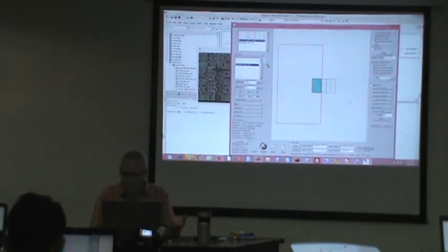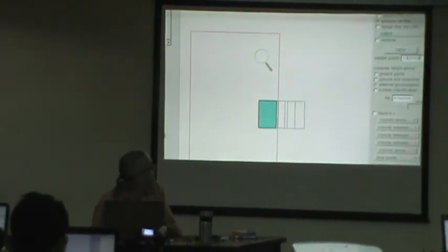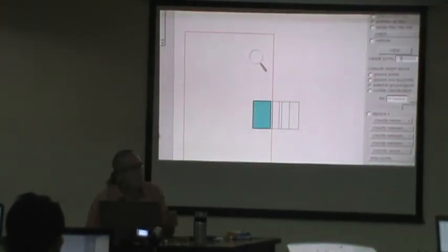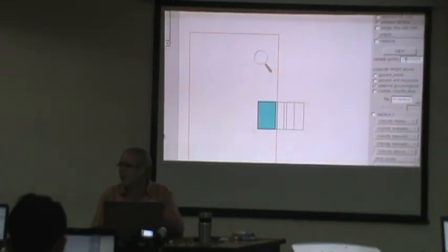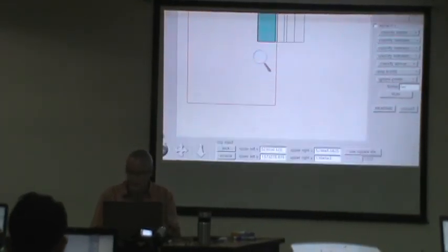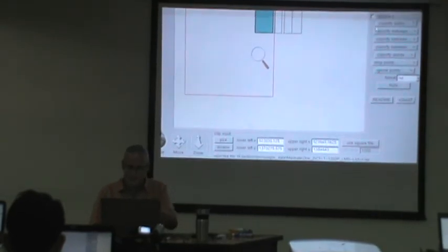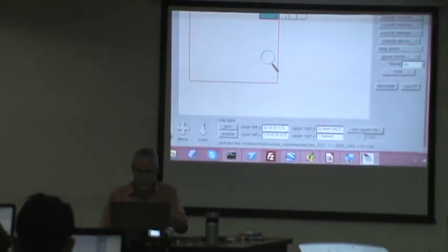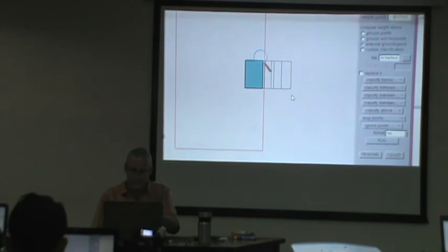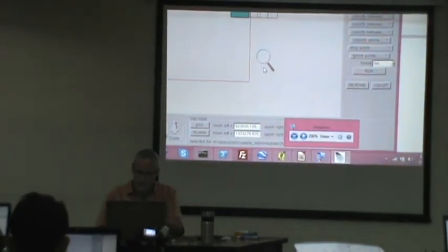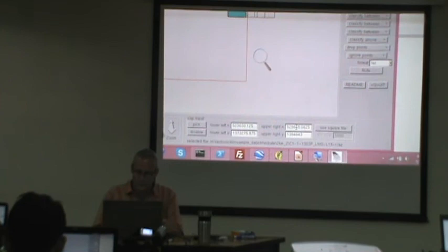There's always a little triangle monster to eat the very big triangles. So I need to run my viewer again. I'm also viewing more points this time. I put the points up to 10 million. I haven't really mentioned that before. Last view removes points, so you don't have all the points. It just samples a few to give you an idea of the file. I also make it a little smaller. Maybe you have noticed that. You can directly edit the extent of the picked box here.